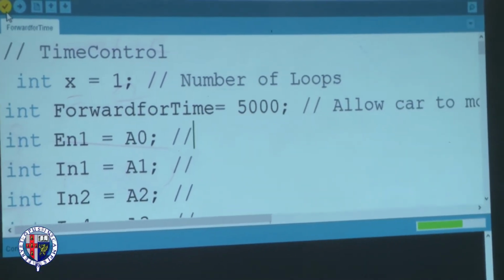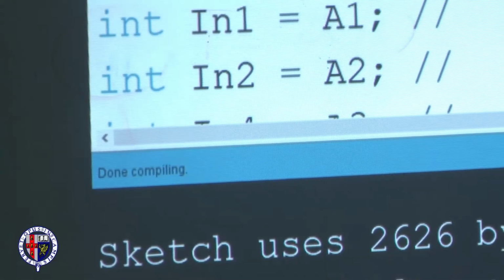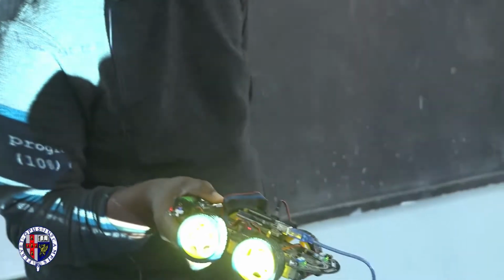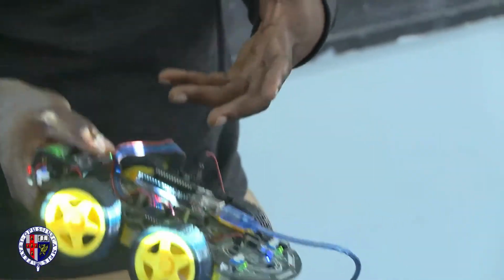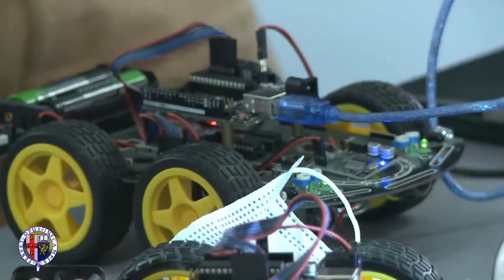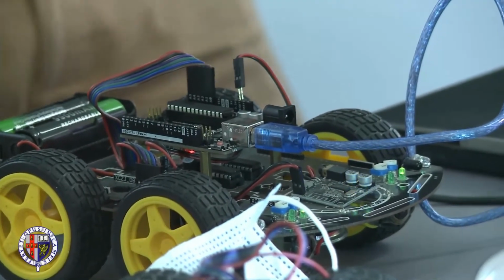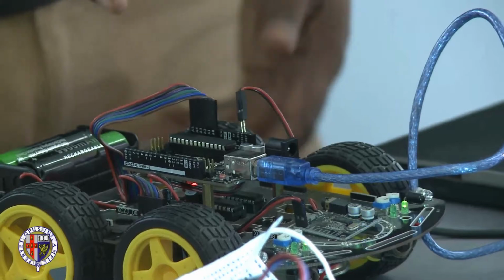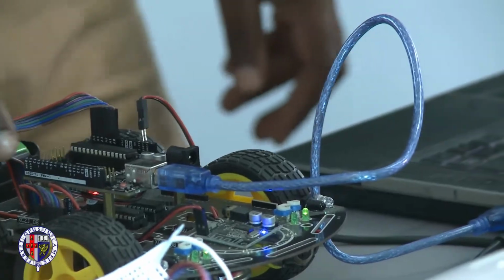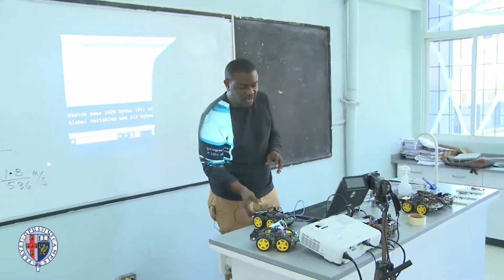If you want to verify, you can verify the code to see if everything is okay. Yeah, it's switched over because now it's on the side for constant acceleration. If I wanted variable acceleration, in electronics we use pulse width modulation, meaning these pins can vary the voltage incrementally, but these pins cannot. So variable is on the right, constant is on the left. I would put a nameplate: this side for constant and this side for variable. It's just moving from here to here, and we have all of the motion scenarios covered.